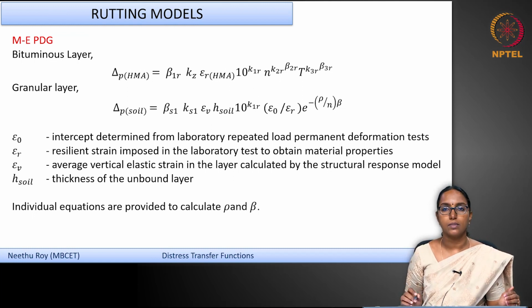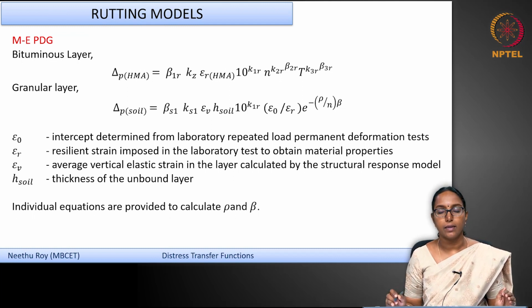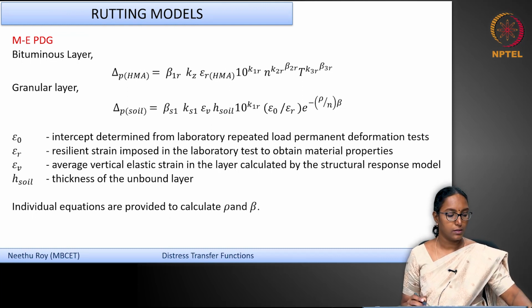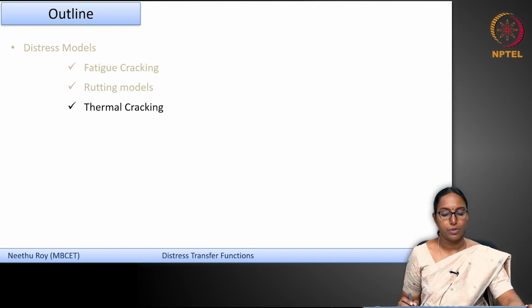Such distress equations can be developed based on the studies that are conducted on the HMA mixtures in the laboratory and the extensive field studies that relate the number of load applications to the permanent deformations that you see in the field. Now let's move on to the third type of distress transfer function that is normally used in many of the design approaches, though this is not used in the IRC approach.